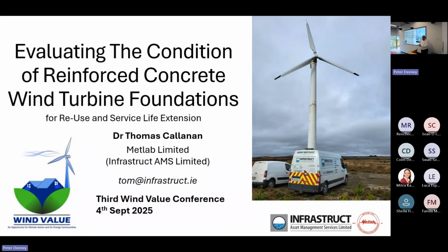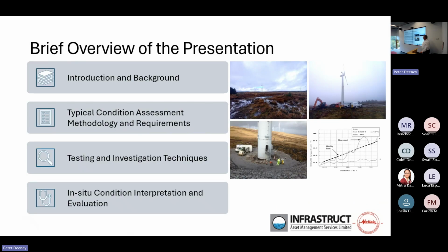And I suppose the idea here is it's a little bit of a curveball, so it's about concrete, but it's more about the evaluation of concrete in the hidden foundations under the turbines. So that's what we're going to look at, the various different testing and investigation methods that we would use to reevaluate and hopefully to extend and reuse the turbine foundations.